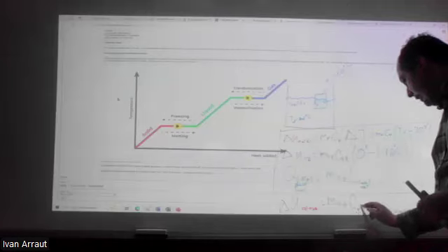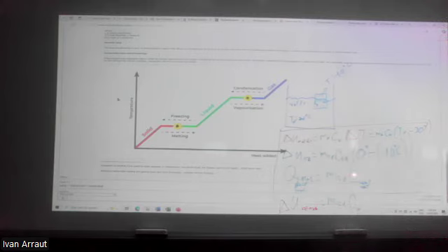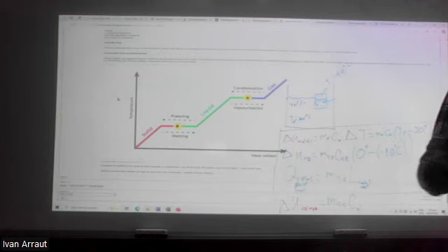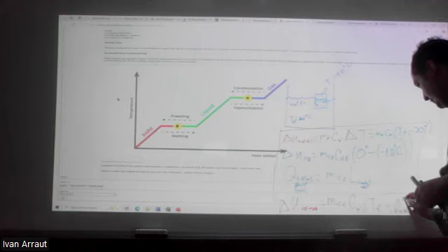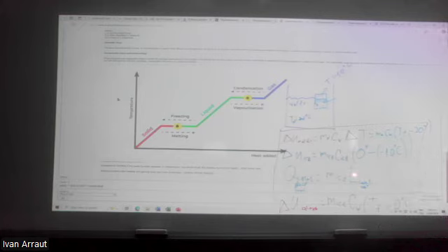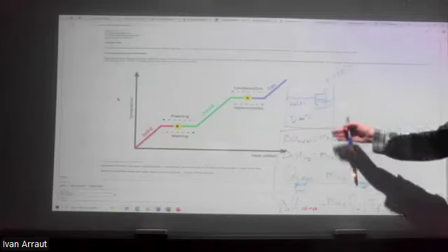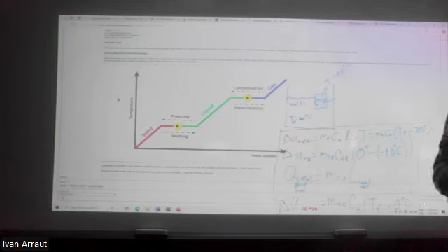Heat capacity of the water, because anyway, it's water, and we are assuming that the heat capacity of the water doesn't change with the temperature, which is not accurate, but still an approximation. Final temperature minus 0 degrees because it comes from 0. So the final temperature again is the only unknown. And later you will solve this. I want you to solve it by yourself because it's not difficult. You will just add this plus this plus this plus this. It has to be equal to 0. Assuming all these heats sum to 0, you solve for the final temperature. And bingo, you have it.